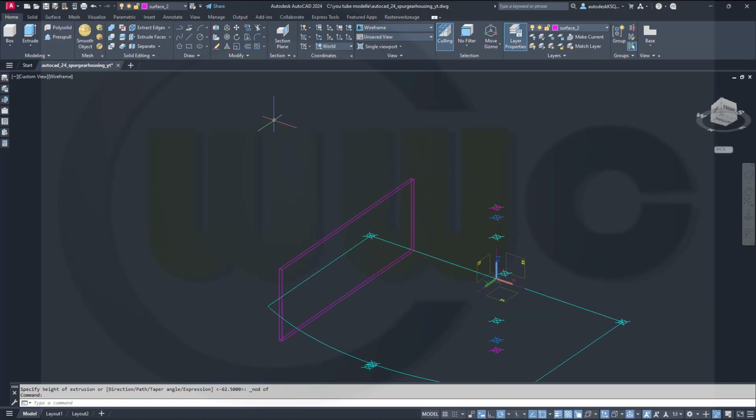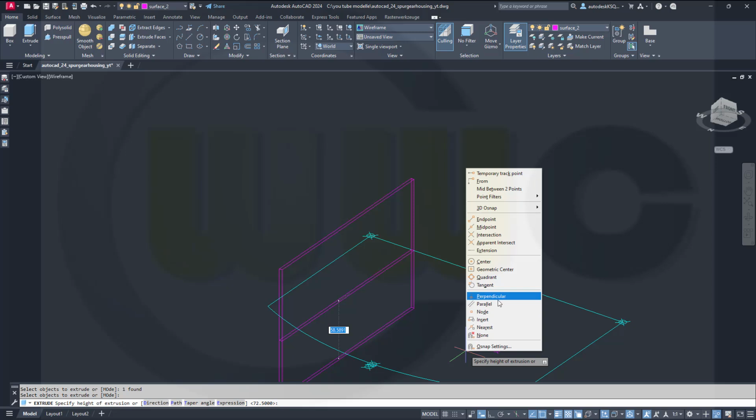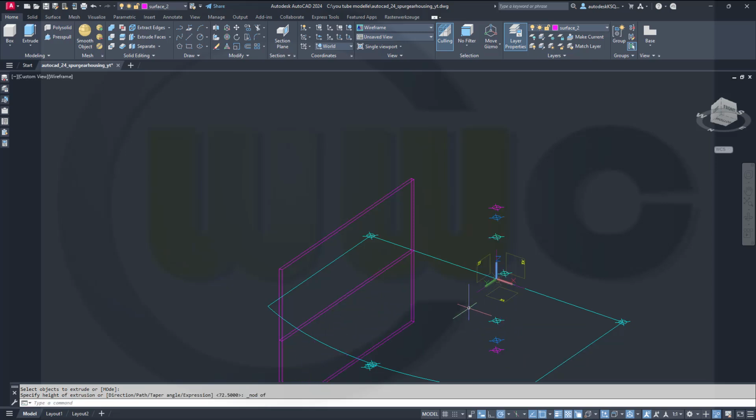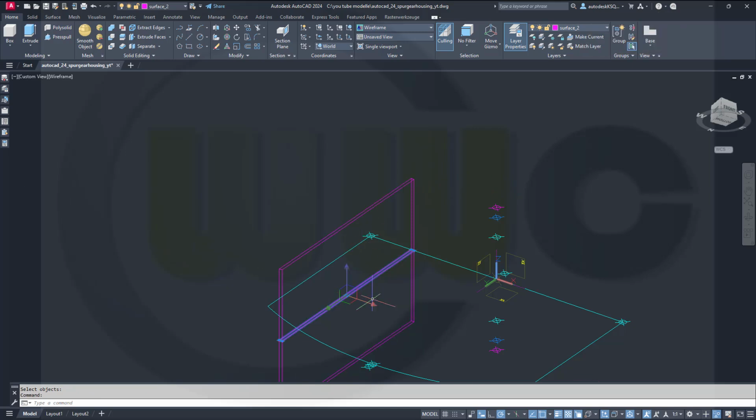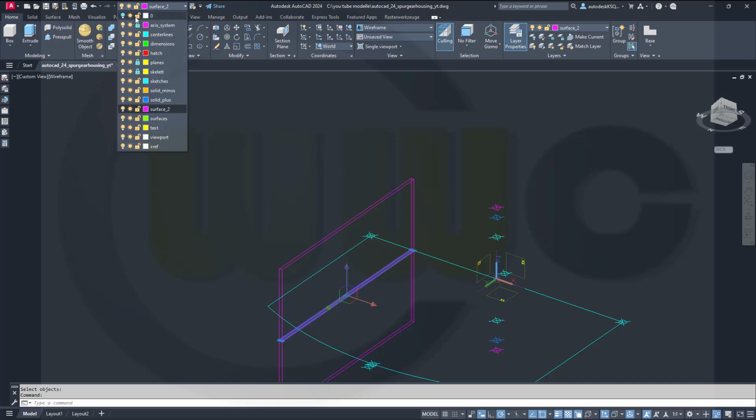Then again on the other side, another extrude with the same polyline. Yep. Right click, enter, and go up to that node here. Where is it? Node, this node here. Go for a union, right click. That's just a sketch, and I can delete that sketch. I don't need it anymore. I could also put it on to layer 0, which is hidden.